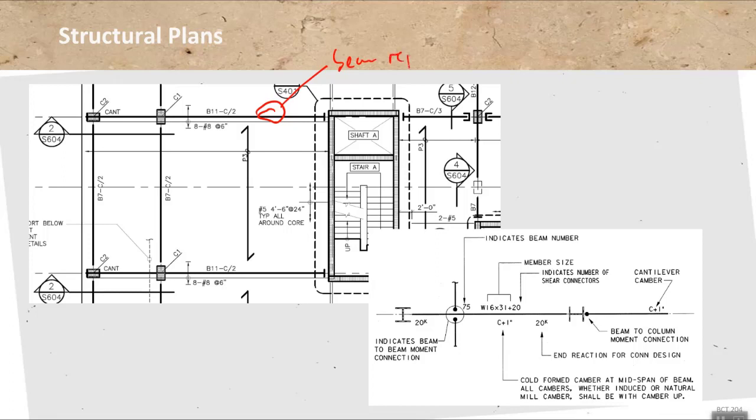So a beam is represented as a thick line right there. What you're looking at on the left here is a plan view. Part of this representation is that you leave gaps where beams frame into other beams. Let me show you how this looks. This would be a continuous beam. This would be a beam that frames into the continuous beam, and there's another beam framing in from the other side. You always leave this little gap, because otherwise you don't know what frames into what.